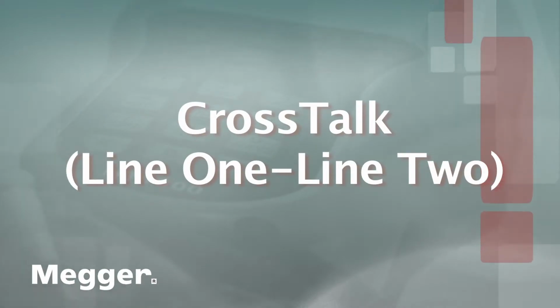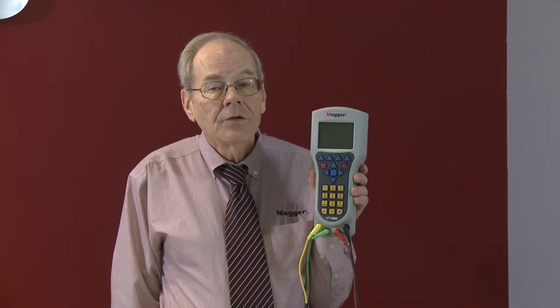Crosstalk, line 1 to line 2. When selected, a pulse is sent out on line 1 and returned on line 2. Line 1 should be connected to the black and red test leads. Line 2 should be connected to the yellow and green test leads.